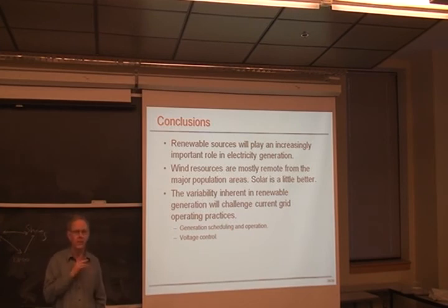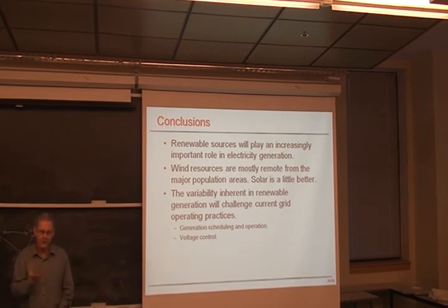There are rules already on emergency conditions that you can drop wind, but that's a really crude way of opening a circuit breaker, and the whole wind farm goes away. And the owners don't like that either. In a more controlled way, there are not the regulations, the sort of procedures in place at the moment, as far as I know, for deliberately shedding wind in a fast response.